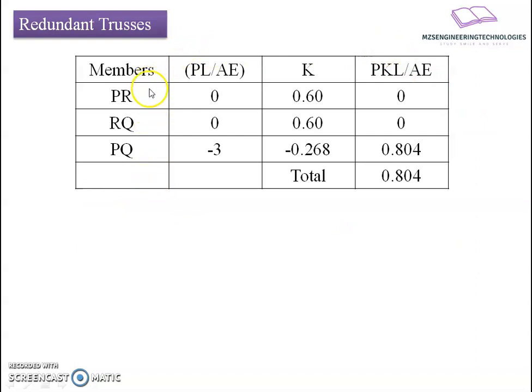The very first column will be the members PR, RQ and PQ. Then I am taking the product PL upon A, which is the individual deformation of the member. For PR there is no deficiency observed, that's why I am putting 0 here. Similarly, for RQ there is no deficiency, so 0. And PQ is short in length, meaning it has lesser length, so I am going to put the amount of shortage it has, which is nothing but the initial deformation given to us, that is minus 3 mm.